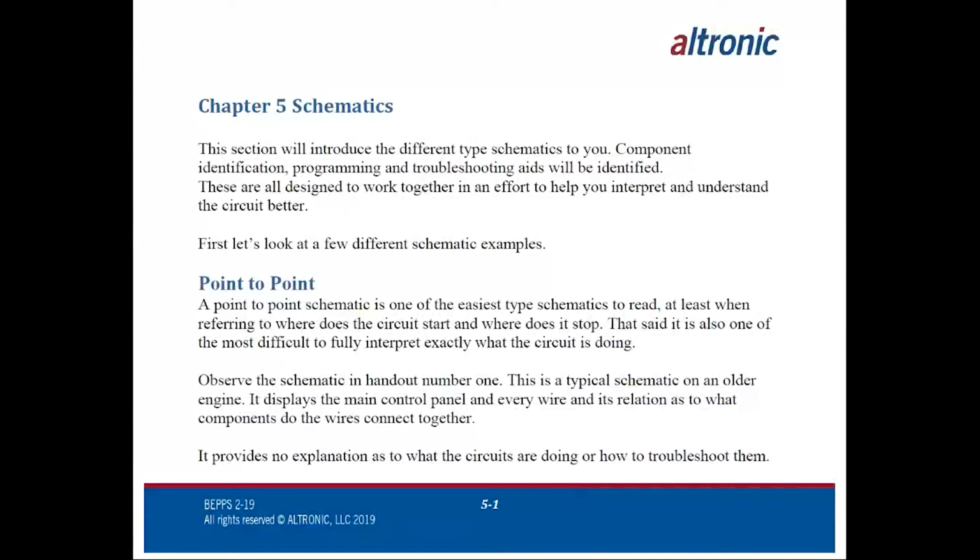Forgive me, these are originally Randall McKinney style map schematics that I've condensed, so they're not going to look really good, but the first one we want to talk about is just a point-to-point schematic, which is one of the easiest schematics to read, at least when you're referring to where does the wire go, point A to point B. While they're the easiest to read, where does this one wire go from point A to point B, it also is the most difficult to interpret what the circuit is doing.